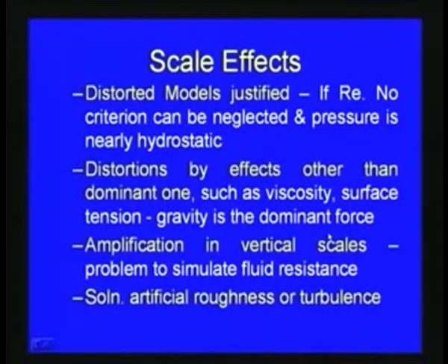While doing these kinds of models, we should be very careful that the scale effects are considered, and the corresponding rectification should be done before the model results are transferred to the prototype, either for design or for construction purposes.